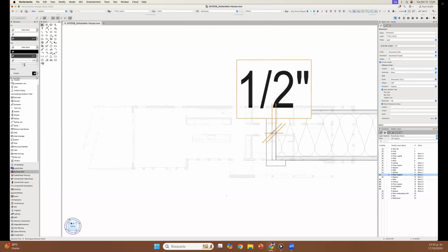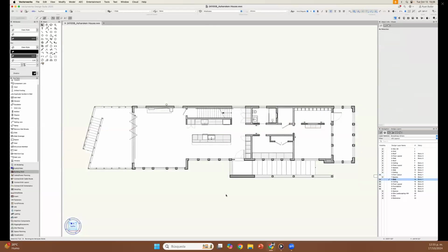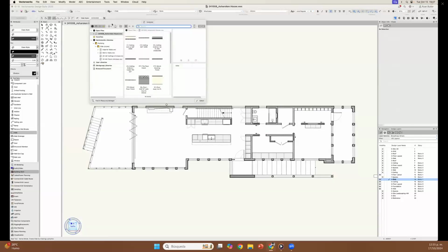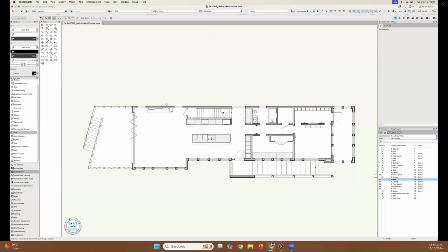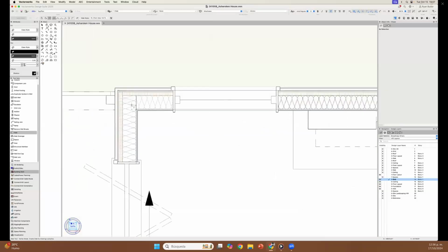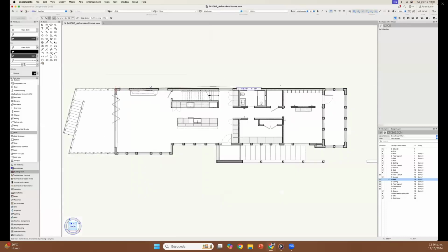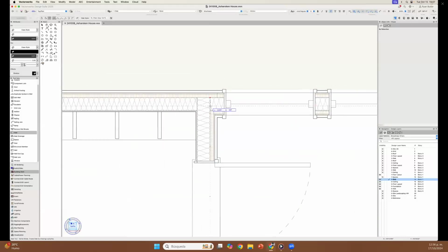Okay, let's take a look at drawing slabs and modeling slabs. In the building shell tool set, there's a slab tool. When you click the slab tool, you can go with an unstyled slab or you can go with a styled slab. Let's go to first floor assembly slab style. Now, if you look at the mode bar up here, you can see pick mode, picked walls mode, vertex mode, inner boundary mode. I'm going to do vertex mode because I like to draw the slab on the outside of the framing of the wall.